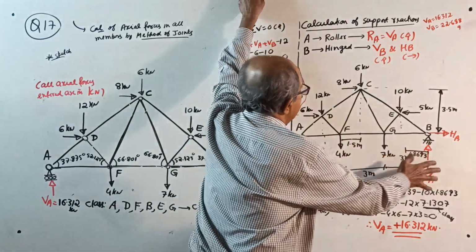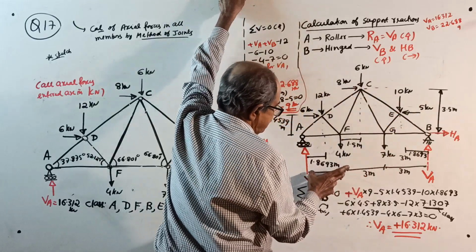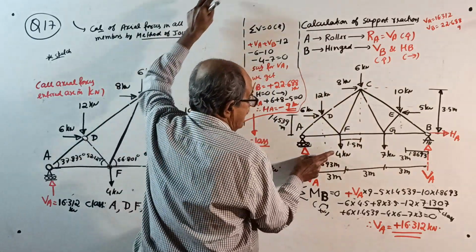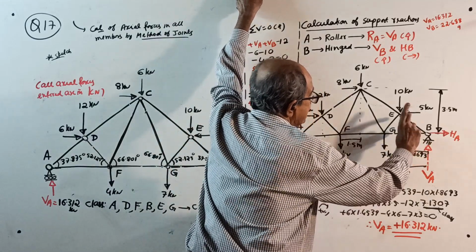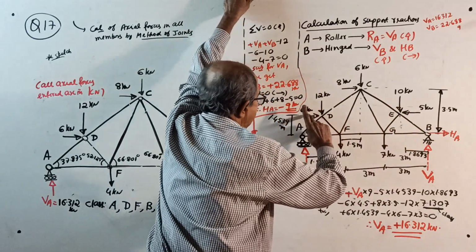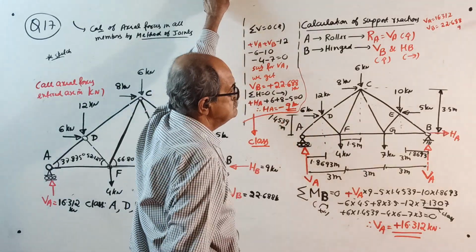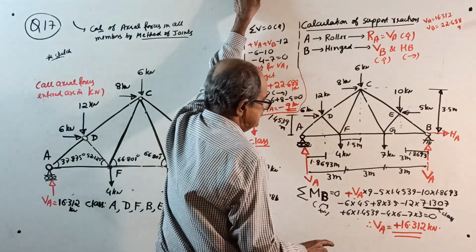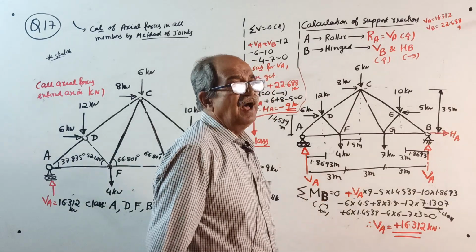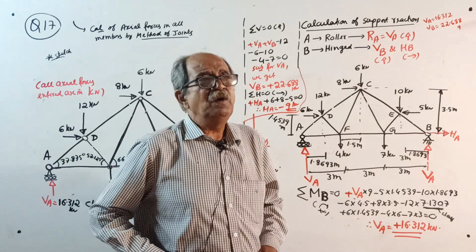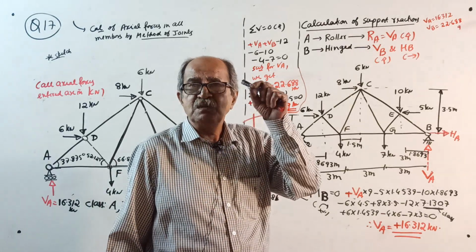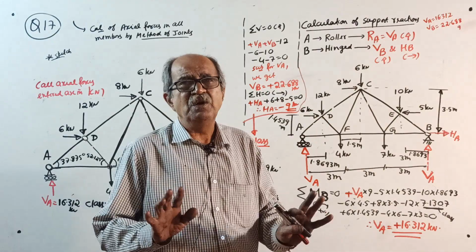Okay. Then, I entered all the forces. See, 3, 3, 3. 1.8693. We got it. I already got it. This also 1.8693. This height and this height both are same, 1.4539. Full height is 3.5. Start. Take moment about B. Why B? You write here. I told you, whenever you find reactions, when you apply sigma M equal to 0, always take moment about the point where unknowns are more. I told, make a practice.